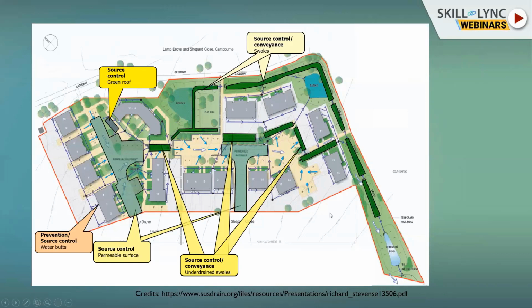After that, again, some of the surface flow was remaining. So for that, we proposed site control measures, providing some detention basins. Some of the play areas we converted into small basins where we can store excess water. When rainfall is very heavy, some water can go into these basins.